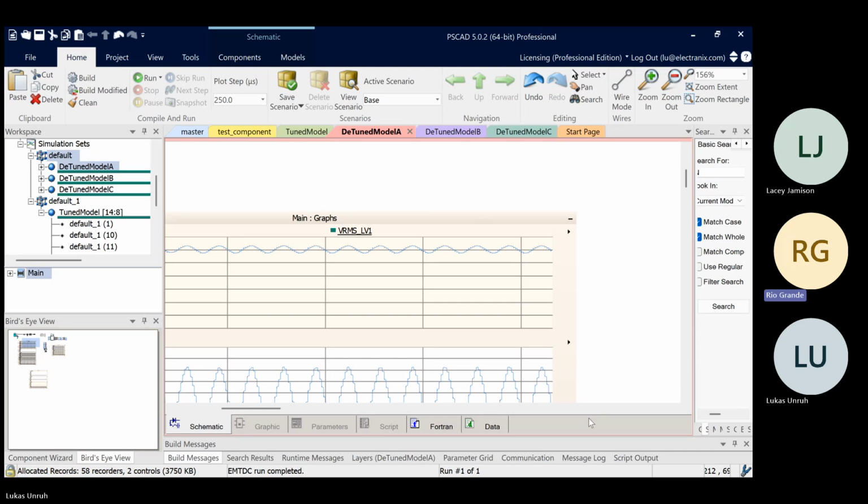And of course, the other danger is that you tune them for the strong system, and now you lose that line, and the system's weak again. That causes a problem. That piece is very important too: it's not just system intact when you're considering system strength. The lowest system strength, the weakest system strength for the worst contingency, is really what you should be tuned for.